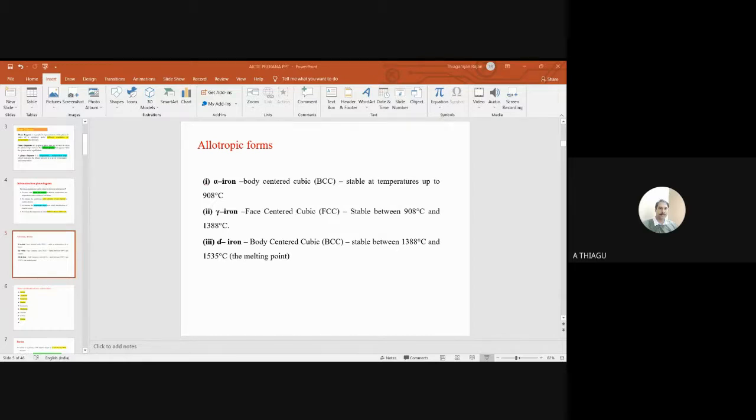If you have more than 0.8% of carbon, we can call it hyper-eutectoid. If it is less than 0.8% of carbon, we call it hypo-eutectoid steel. I already pointed this out in the iron-carbon diagram at the bottom itself. Once again, if possible, note down this percentage of carbon for the steel categories: eutectoid, hypo, and hyper.